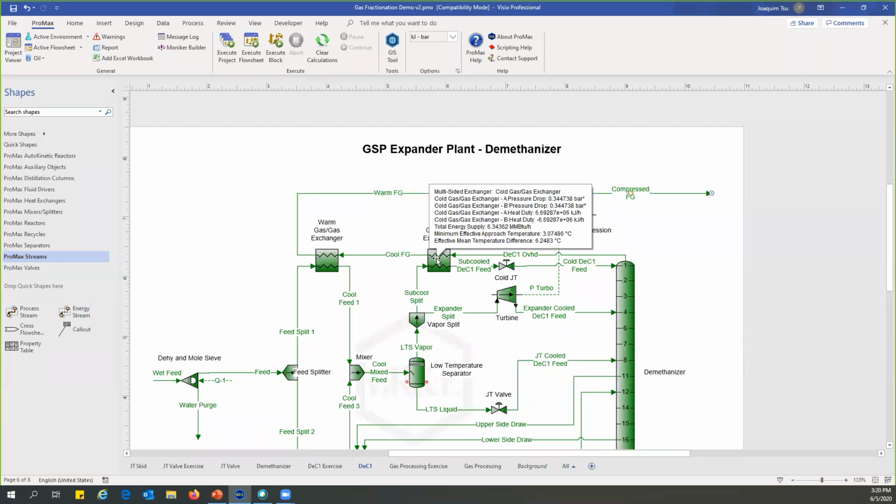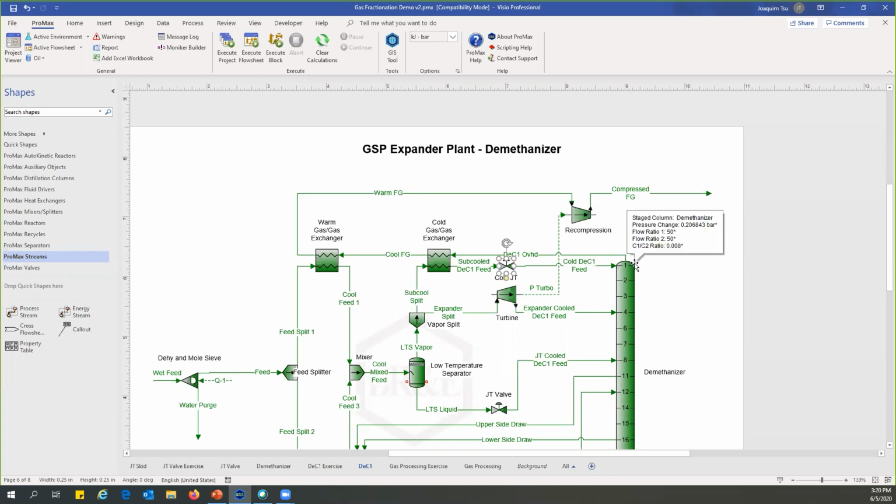It has to be basically almost all liquid. And you have some JT valve, and then you drop it down, because if you were to just put vapor into the top tray, all the vapor will just leave with the top, and you're not really having any vapor liquid interaction. You want liquid methane reflux action with your vapor ethane, so that you can wash the vapor ethane back down.